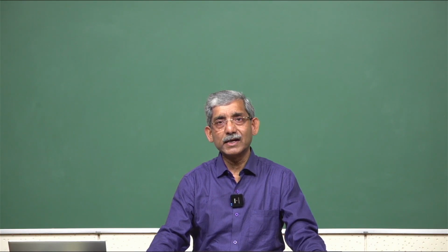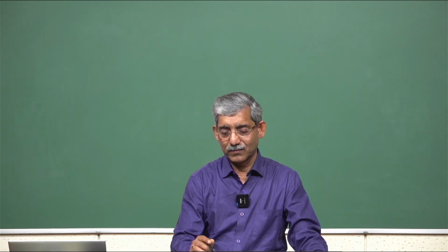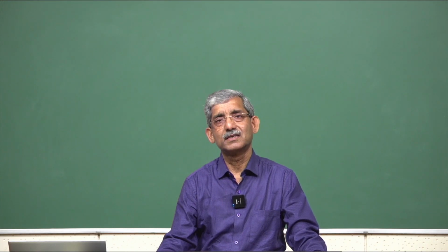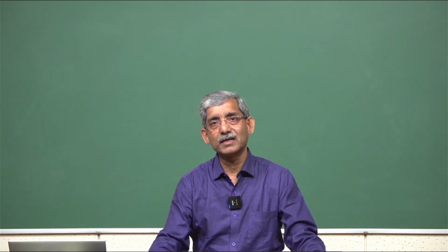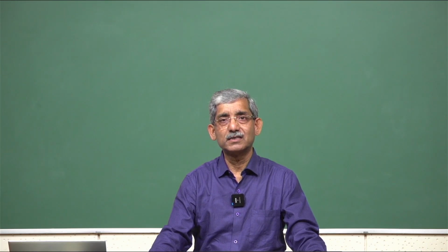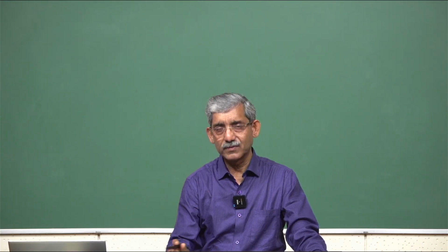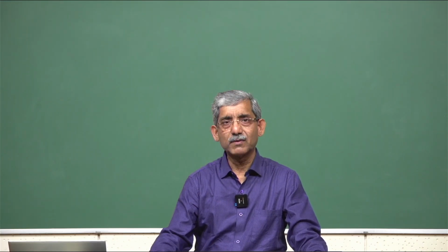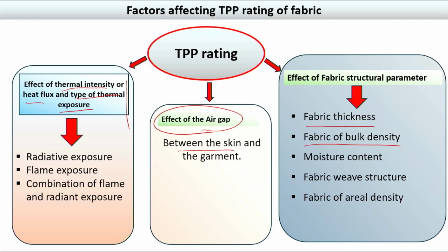And the fabric related parameters: the fabric thickness is there. If we change the fabric thickness, the TPP rating will change. Fabric bulk density, if we increase the fabric thickness, TPP rating will increase, like that. Moisture content in the fabric, if we change the moisture content, then TPP rating will be different, keeping air gap and other parameters the same. So, the TPP rating will change with all these parameters.